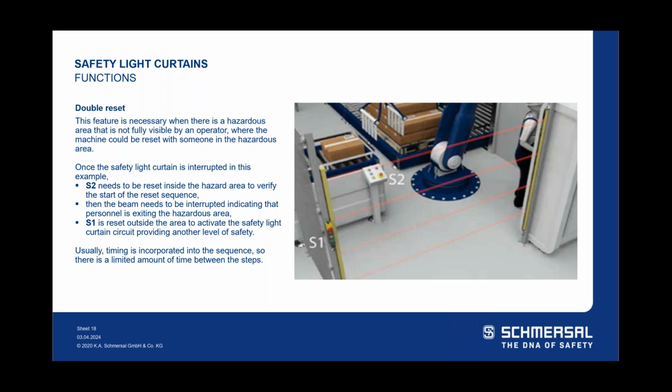What I mean by that is they could be in there fixing or working on something, but not be seen by a passerby. What we don't want to happen is somebody in there, they've obviously broken the light curtains, okay? They've stopped the hazardous process while they're working. We wouldn't want someone to be able to walk by, and S1 is your reset button. Somebody says, oh, I wonder why this isn't working, maybe it was tripped somehow, and resets it and puts that operator in a very vulnerable position.